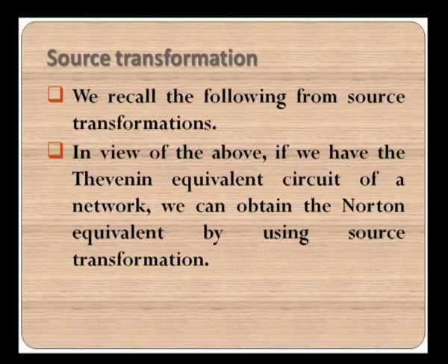If we know how to find the VTH value, very easily we can calculate the IN, and that IN could also be used in the network analysis. We recall the following from source transformations. In view of the above, if we have the Thevenin equivalent circuit of a network, we can obtain the Norton equivalent by using the source transformation technique.